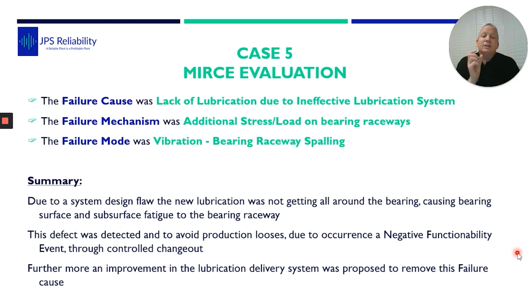So in this case, the vibration analysis was an indicator, and it would have been a predictor if we had trending, because you could have trended it, and as that damage got worse and worse, the peak waveform would have gone up and up and up. And now we know at what level that bearing is really bad. We can use vibration analysis, a condition monitoring tool, as a predictor for the health of the system.